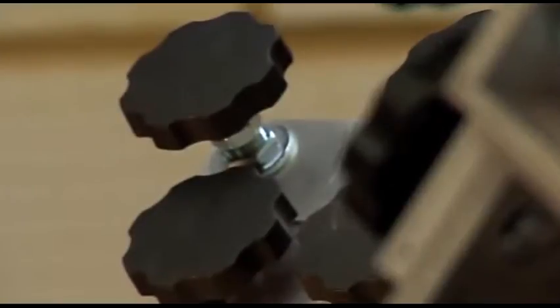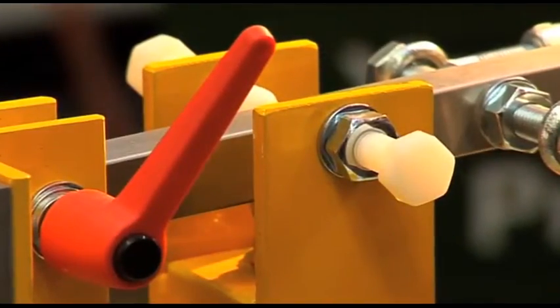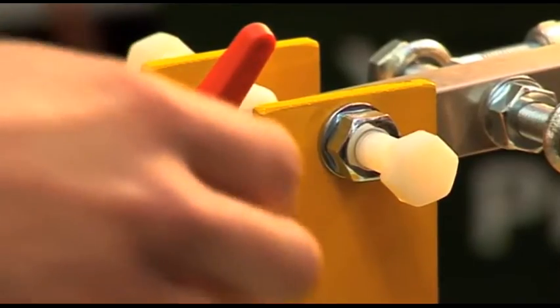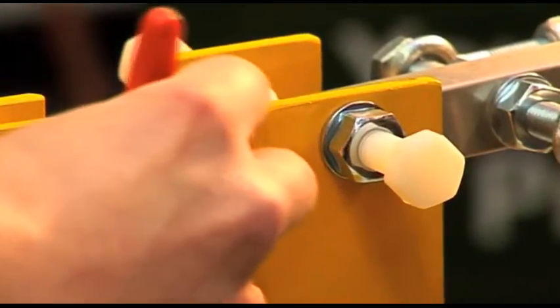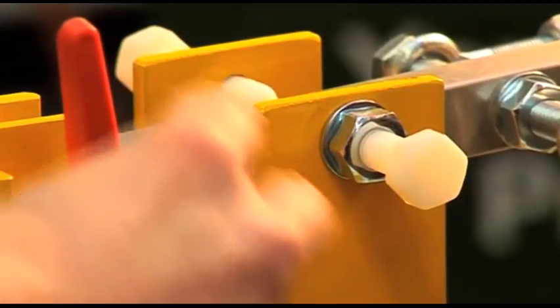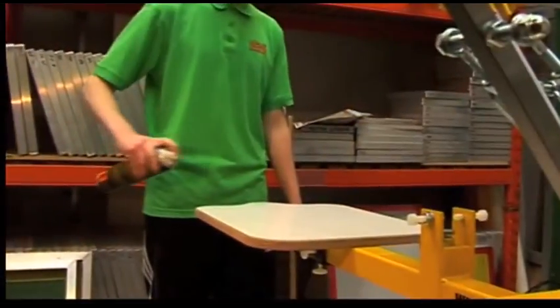We now need to ensure that your screen is level and at the right height. As we are printing with a dark ink, the screen should sit about 1/8 of an inch above your shirt. Adjust the orange lever to achieve this. If you are printing with white ink onto a dark garment such as black, it may benefit to decrease the off contact and apply less pressure to the squeegee.